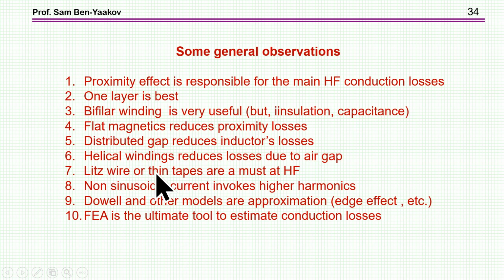Litz wire or thin tape is really a must at high frequency. There's no way around it. At very high frequency, you need either very fine Litz wire or a thin, very thin tape. Now I'm talking about frequencies of hundreds of kilohertz, not to mention 1 megahertz. Well, 1 megahertz is becoming a very tough problem, okay, because of the very high frequency and the very thin skin depth. And also we have to take into account that in many applications, the current is non-sinusoidal, so you have to consider the fact that there are higher harmonics.